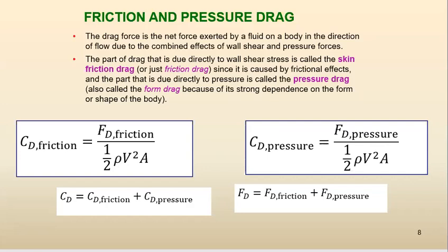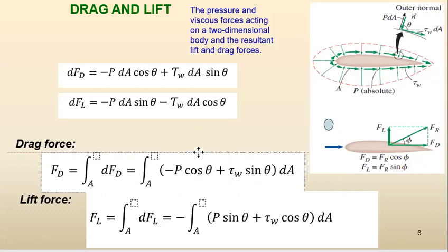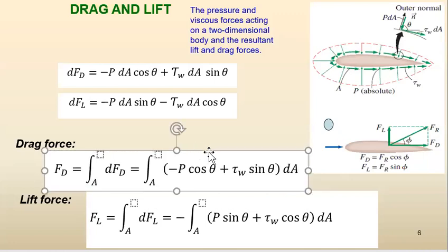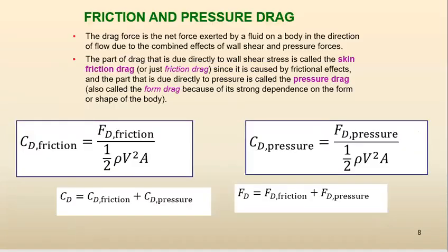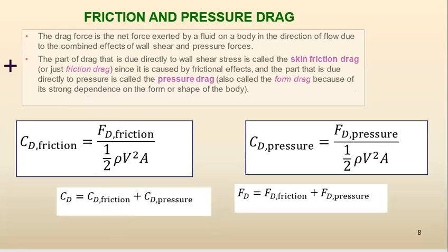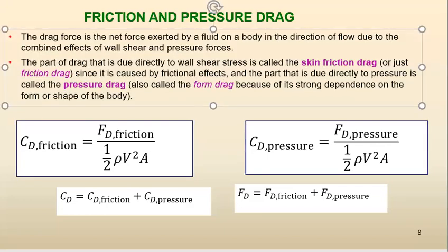That's what I mentioned here. You have a pressure component and a shear component. The same here: for lift force also, you have pressure and shear components. That's why we may resolve the drag coefficient into a drag coefficient correlated with friction and a drag coefficient correlated with pressure.